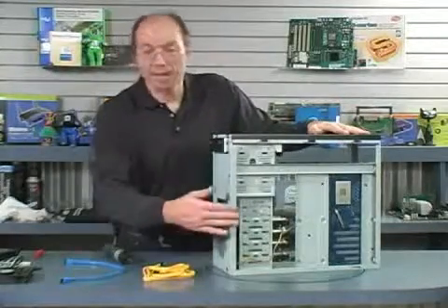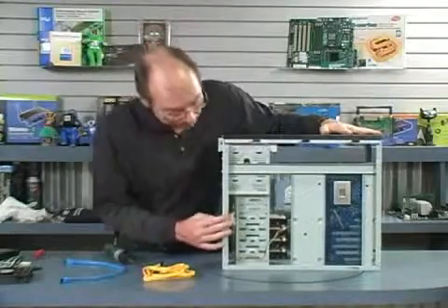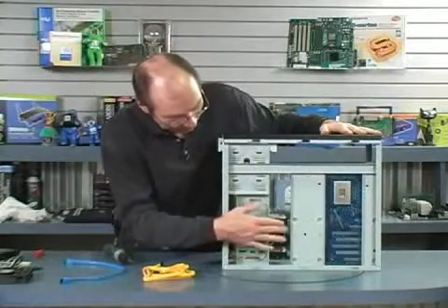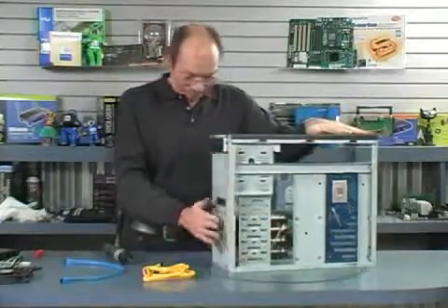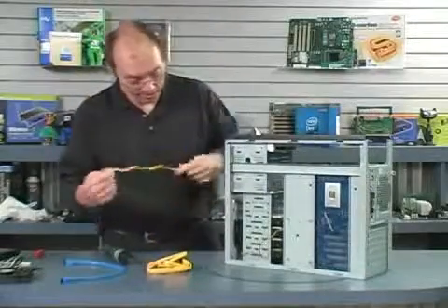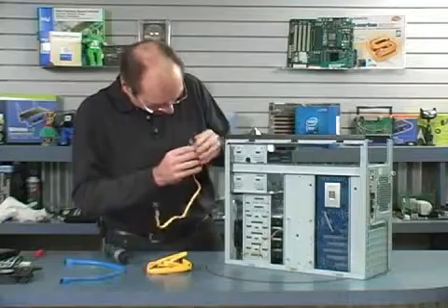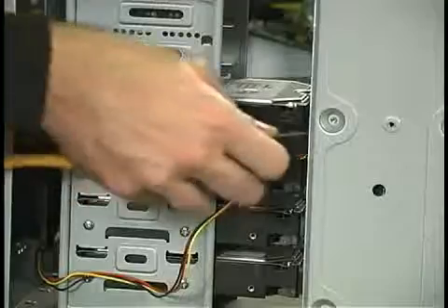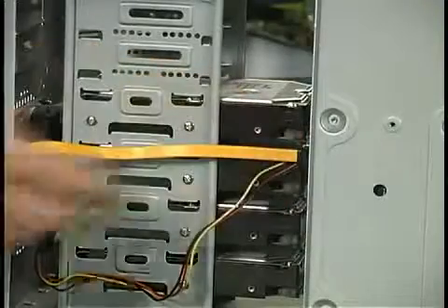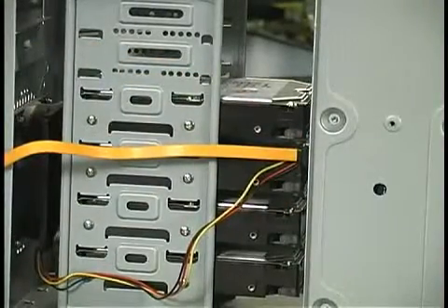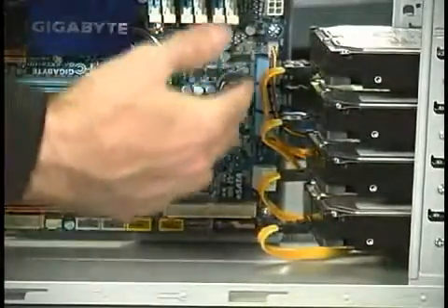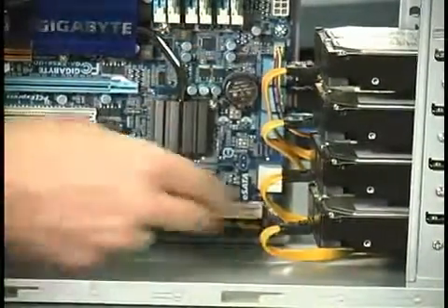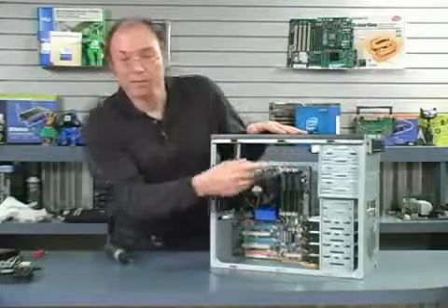Good thing that the back panel comes off of this case, because it makes getting to this a lot easier. So I'm basically going to connect the 4 hard drives and then the optical drive cable. So I'll start with the first one here. Get all these cables plugged in, and then we'll connect them up to the drives. There, I've got the last cable plugged in. All the drives are now connected to the SATA ports on the motherboard, as is the optical drive up here.